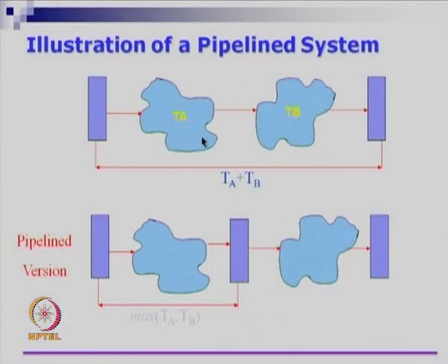So, in terms of a picture, usually for pipelining people draw what is called a cloud diagram. So, let us say this is the block A, which could be the multiplier, and this is block B, which could be the adder. Then without pipeline, the set of inputs going through some combinational logic going through this would have a delay of TA plus TB.